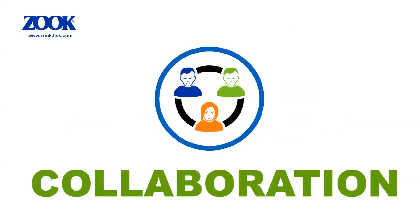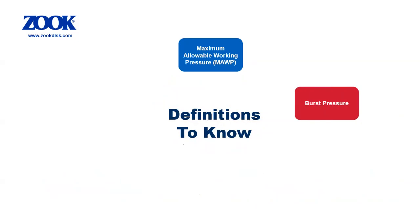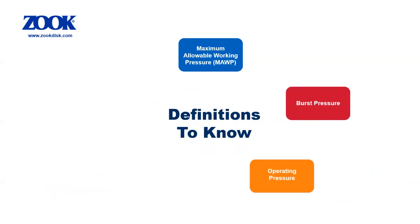As you can see, selecting the best possible rupture disc design is not a simple task for any one person to tackle on their own. Good collaboration between the end user, system designer, and disc manufacturer is essential in getting it right the first time. Every application has both common and unique criteria that will guide the selection process. Common criteria include the following: vessel maximum allowable working pressure, disc burst pressure and temperature, normal system operating pressure, operating ratio, and burst tolerance.